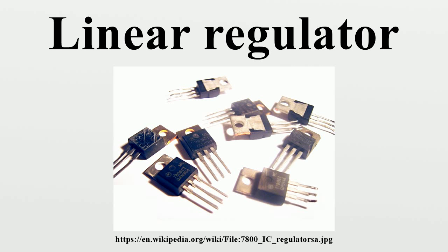All linear regulators require an input voltage at least some minimum amount higher than the desired output voltage. That minimum amount is called the dropout voltage. For example, a common regulator such as the 7805 has an output voltage of 5V, but can only maintain this if the input voltage remains above about 7V, before the output voltage begins sagging below the rated output. Its dropout voltage is therefore 7V minus 5V equals 2V.